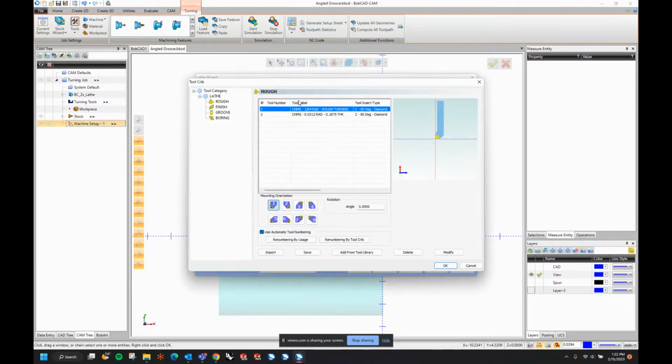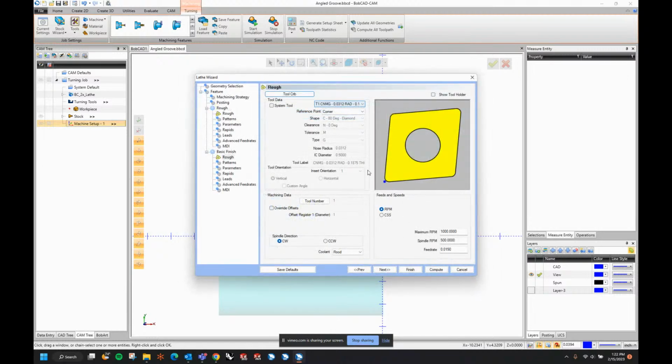And actually, it's not tool number 1 because I changed the radius. It's tool number 2. Now, if you're in version 35, you can also do that here from this drop-down menu. You notice now I only have 1 tool here because it overwrote the auto-selected one.